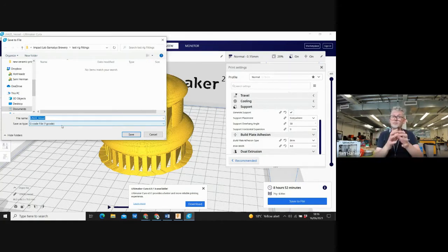G-code is the information that goes from Cura to the machine itself. So we've had CAD CAM. CAD is our Fusion file. CAM is a machine. And Cura has taken our design and translated it into the code required to go to the machine. So in that sense, it doesn't really matter what printer you've got, because whatever printer you have will have its own software which will do this job and translate it for us.